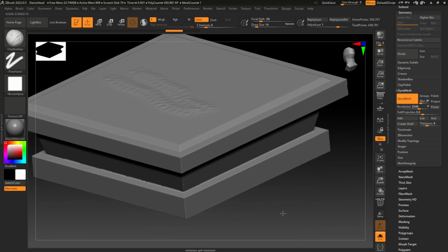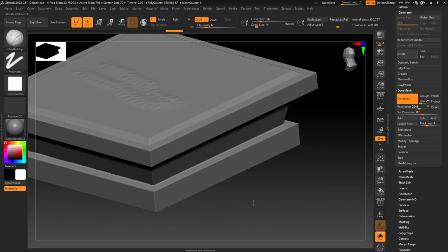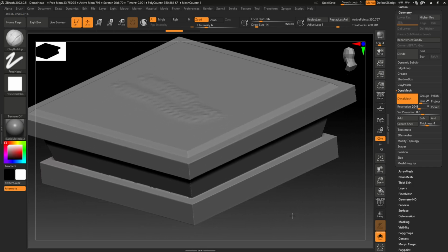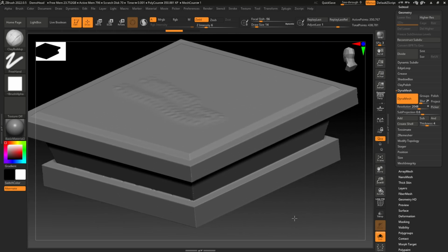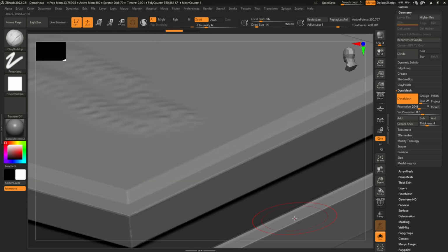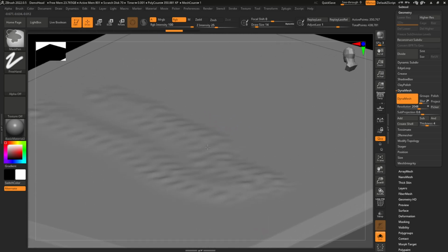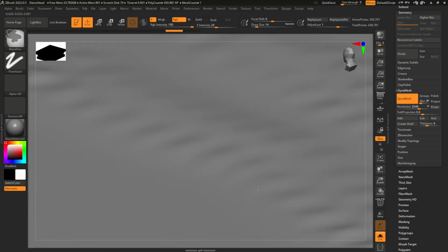Alt and your regular right mouse or left mouse. What is happening here is panning. If you want to pan the camera, it is Alt and your right mouse button. This is your camera panning. For zoom in, zoom out, Control and right click. First place your mouse where you want to zoom in. Just place it over here and press the Control key. I want to zoom here, and then start zooming that particular area.